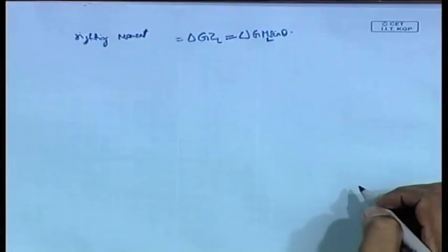We discussed the righting arm GZ, and we talked about the restoring moment delta into GZ, and we have said that GZ is equal to GM sin phi for heeling. The same principle is holding here. Delta GZL is the longitudinal righting moment. So, delta GZL is equal to delta GML sin theta.